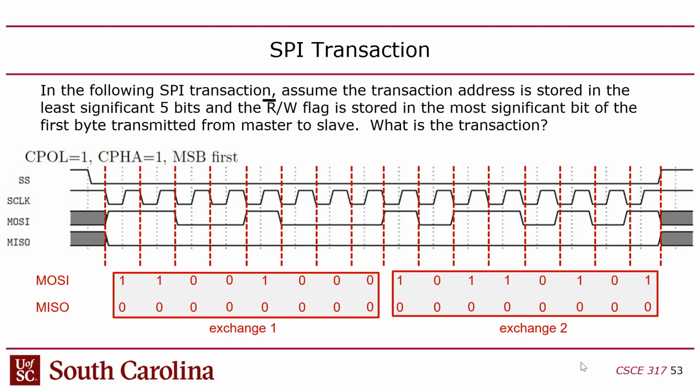Now you might say, well, wait a second, why not just show the bits there on the timing diagram? Why have a timing diagram where you have to interpret a graph to determine whether it's 0 or 1? Well, it's meant to look like a logic analyzer or an oscilloscope, right? This is meant to actually indicate a voltage up or down, so you have to interpret these lines as being high or low, and you're just translating. So in this case, that's 1 1 0 0 1 0 0 0 1 0 1 1 0 1 0 1, and those are marked on there.